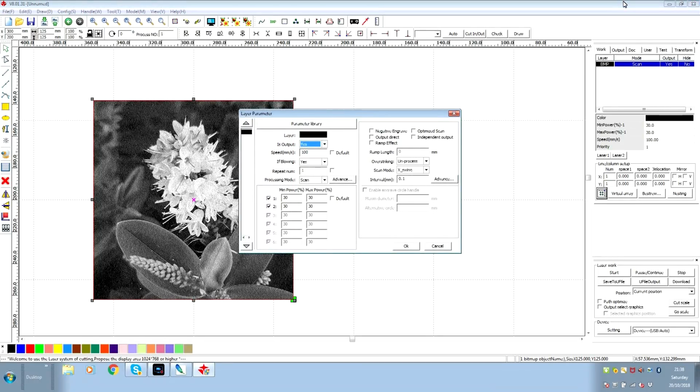We need to set our parameters. We know that we can run generally at about 200 millimeters a second. Output, yes. Blowing, no. Scanning, yes. Well, we only need to go probably at around about 11 or 12 or something like that on my 60-watt tube. And the interval, well, we've set this to 254, which is 0.1. X swing, fine. No ticks up here.